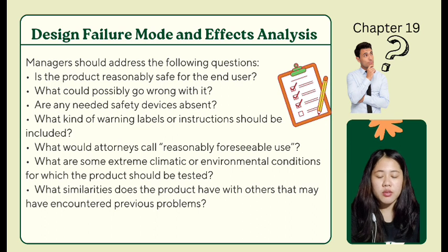Are any needed safety devices absent? What kind of warning labels or instructions should be included? What would attorneys call reasonably foreseeable use? Or what are some extreme climatic or environmental conditions for which the product should be tested? What similarities does the product have with others that may have encountered previous problems? So that's what a firm should consider when doing a test.